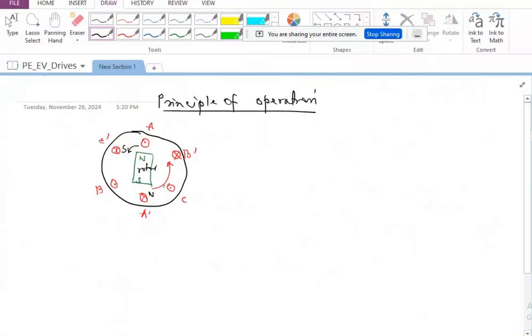So if the rotor is already up and running, it would be able to lock up with your stator revolving magnetic field pole. But if the rotor is starting from zero speed, while the stator revolving magnetic field is already rotating at a very high speed like 3000 RPM, this North Pole will slowly try to move towards the South Pole, but by the time it makes up its mind and locks up with the South Pole, this North Pole would already have reached the other side.